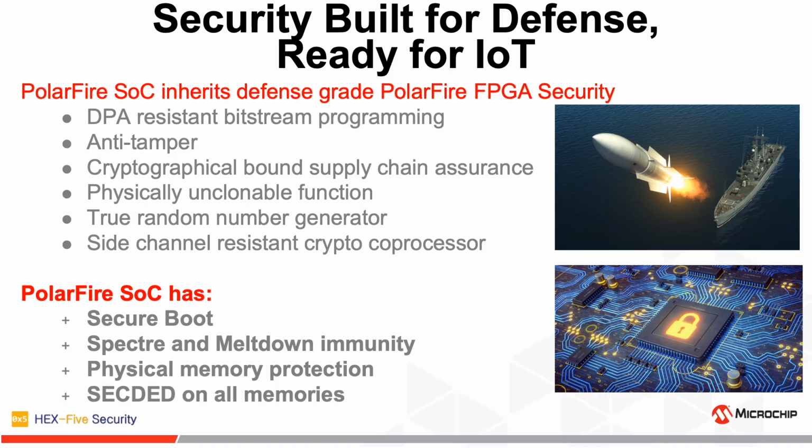And we have error correction on all the memories. Typically it's a reliability function, but it really is germane to security as well. Any kind of memory, we will correct single bits and detect 2-bit errors. And these error signals are actually brought to the FPGA fabric so that you could do something with them in your logic, because at that point in time, if you get a 2-bit error in some memory that may contain your stack, your system becomes unreliable and unstable.